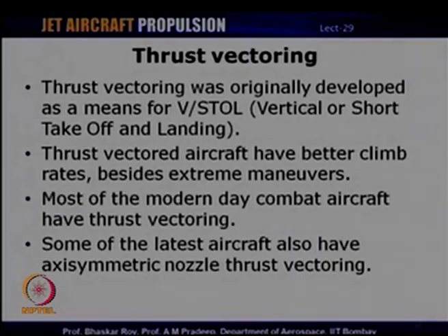And as I mentioned, it was originally developed for achieving vertical or short takeoff and landing, and it is still used in some aircraft with vertical or short takeoff and landing, like for example the Sea Harrier, where the nozzles can be deflected in extreme directions to achieve vertical or short takeoff and landing. Now, thrust vectored aircraft obviously will have better maneuvering capabilities. They can also have better climb rates. If one deflects the nozzle, one can achieve very high climb rates which are not really possible